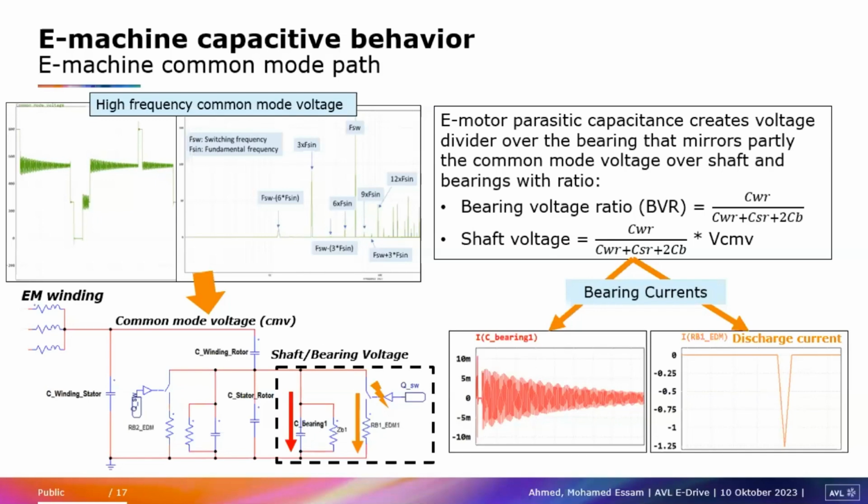There are many kinds of bearing currents. There are circulating bearing currents, which happen more at higher speeds, where the gap between, for example, the ball and the race of the bearing increases. So you have a lubrication that is more insulating, so it takes a capacitive form, and you will see that it discharges through this cap.